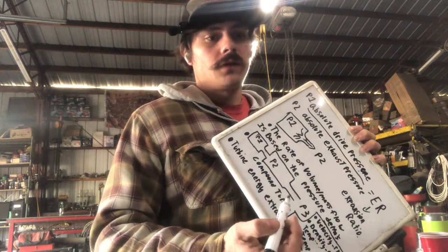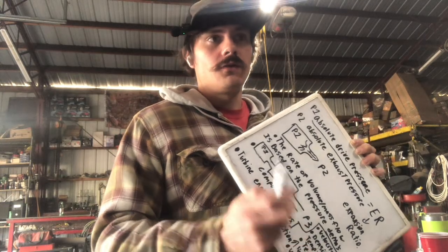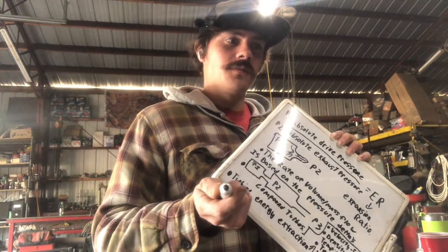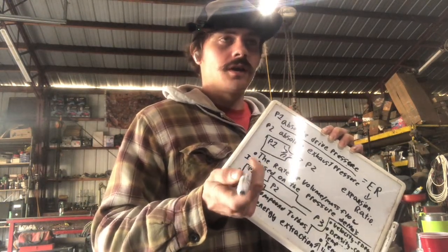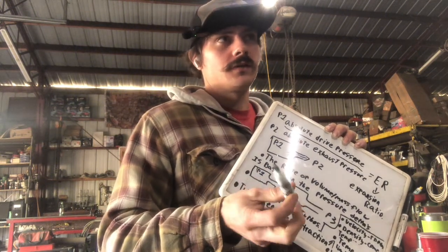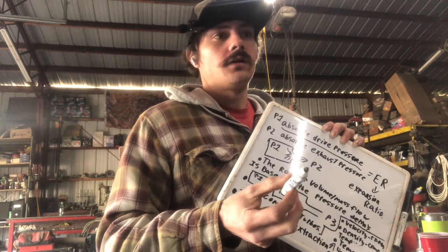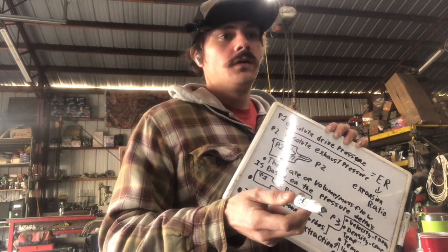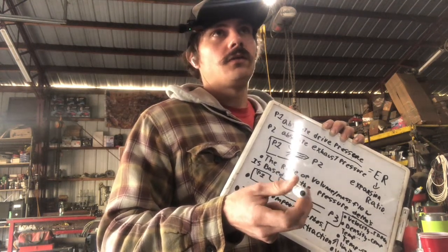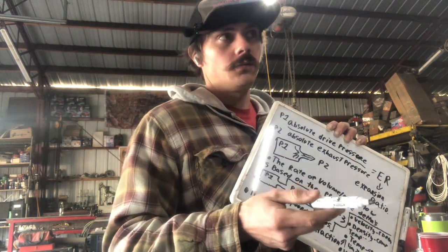And then there's the other one where, like I said, VGTs do it really well. And they give you all the data, which is awesome, on that calibrated power bit. You can go look at it. It's like a 4-to-1 expansion ratio. With the 5-inch exhaust, it's 320 something, I think, with 12 psi, and it's 289, I think, with 15 psi.